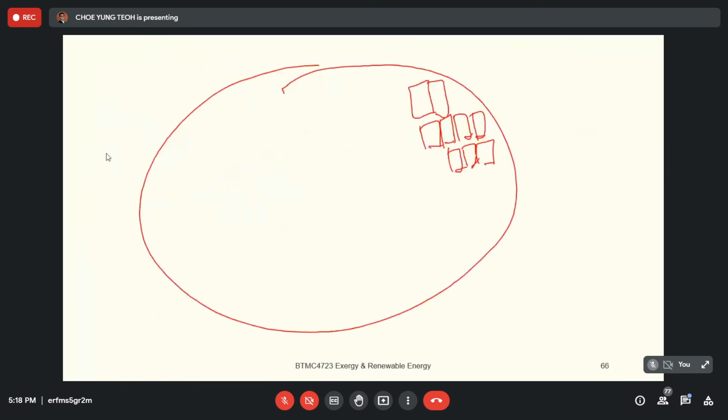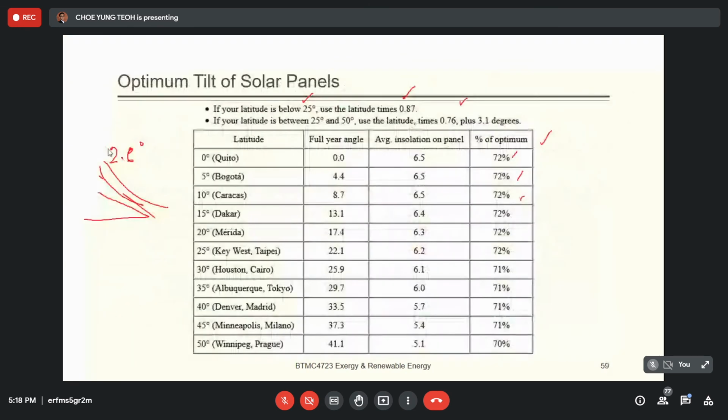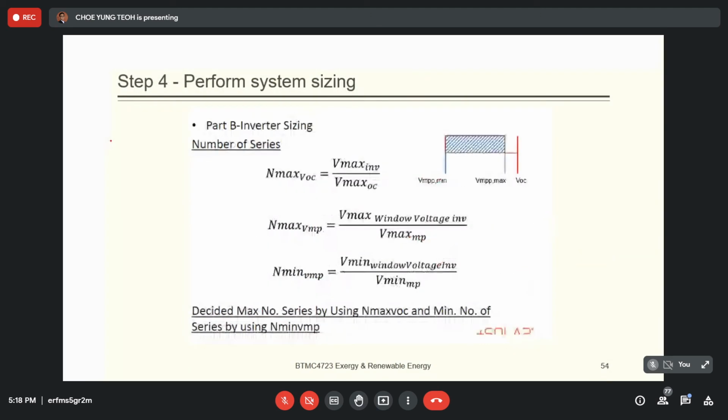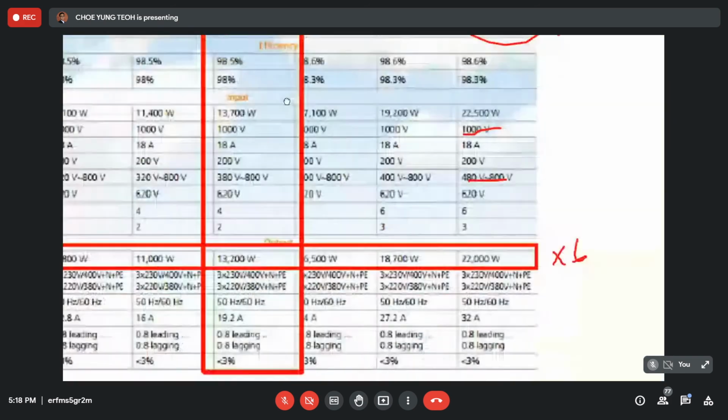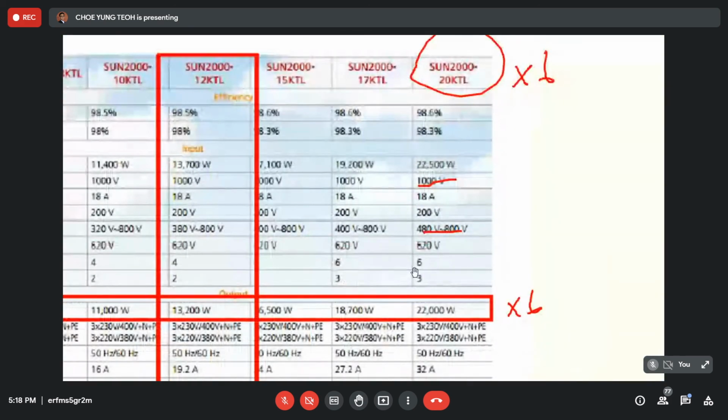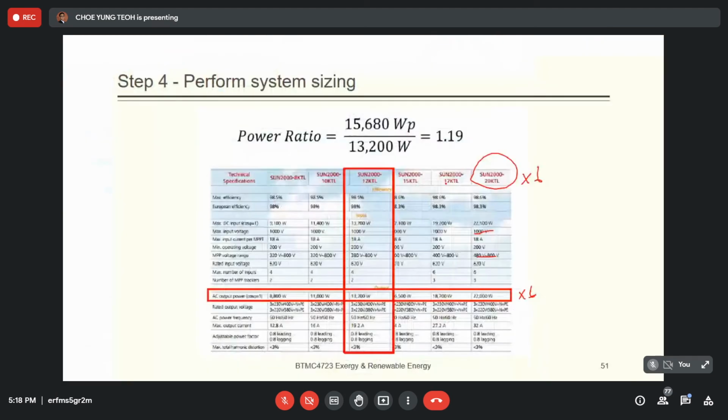So we go back to check on the spec for this inverter. This can have the 6 input per inverter. So 6 times 6, we can get 36 input. So we just need 20, more than enough. And each of the inverter has 3 input, but again, we only need one MPP per inverter. So definitely it beat our requirement. So I can use this.